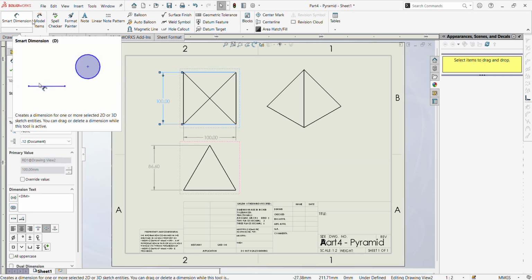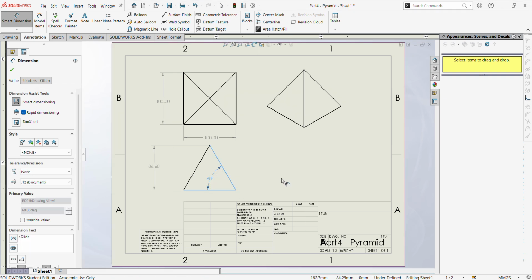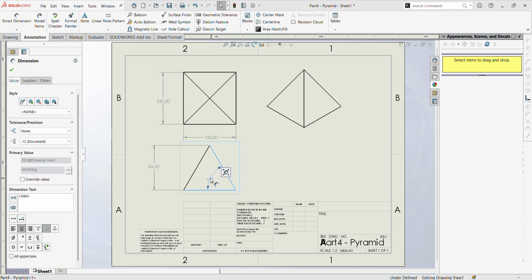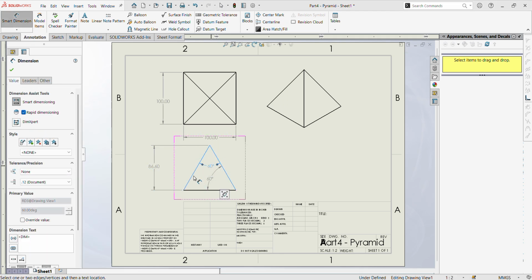Well, not really, because how is someone going to know? You might be able to tell them to extrude to that height, but at what angle? So if you click these two lines, you get that. And you could do, I believe, times 2 here, times 3, because all of these should be 60 degrees, right, if it's completed the angle. But that's kind of just over-dimensioning it, right? Yeah, they're all going to be 60 because it's an equilateral triangle.